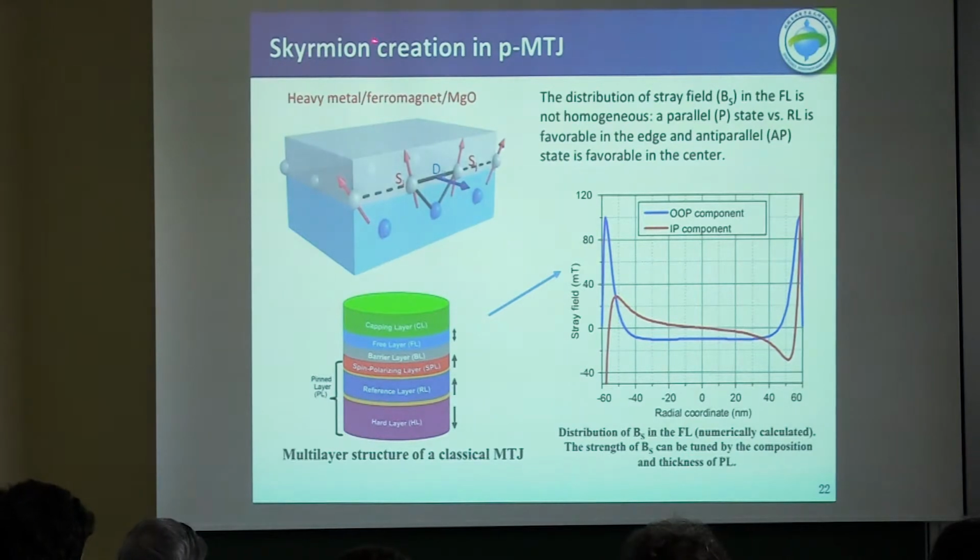So the second synapse that we can imagine is to use skyrmion creation in a perpendicular magnetic tunnel junction. When I wrote the review, I calculated the energy efficiency by using spin Hall current. We always need a very high current density to move the skyrmion. But when we use a spin transfer torque method to nucleate the skyrmion in the MTJ, the energy efficiency could be better. So this is why we also focus on some devices to implement the skyrmion in a magnetic tunnel junction.